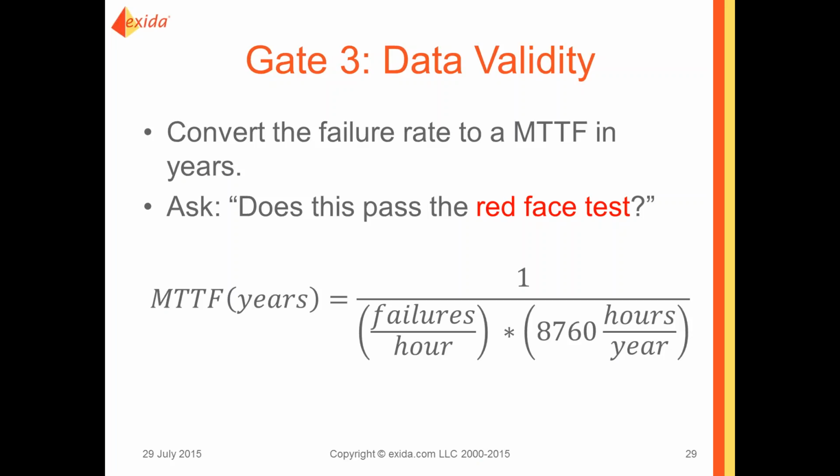We don't deal with them every day. It's a good way to get a real quick check and say, wow, if I had a population of 10,000 valve assemblies, do I think I'd have more or less than one failure per year? Oh, I'd have more, and work through that simple everyday question. And then imagine if you were trying to testify why you felt one failure in 200,000 years was reasonable. I just don't think most people with process experience would think that's credible.